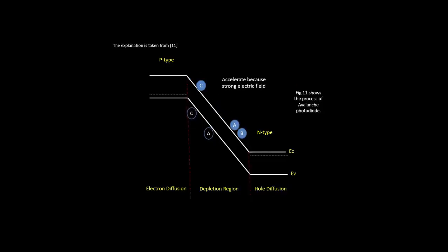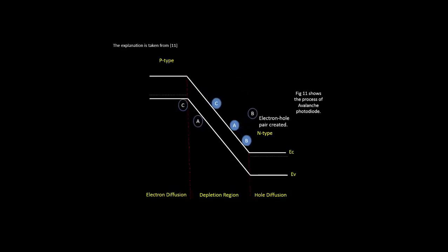These competing processes cause the electron to reach an average saturation velocity. If the energy of the electron is larger than the energy gap at any time during the process, a second electron-hole pair by impact ionization can occur. The avalanche photodiode now has a current gain, introduced by the avalanche multiplication factor. The holes generated also accelerate, moving toward the left. Each of these also has a chance of impact ionizing should they acquire sufficient energy, thereby generating a hole-initiated electron-hole pair.